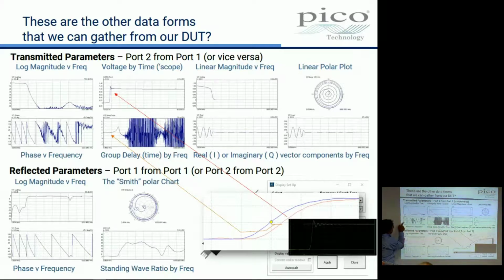Right, this is phase, and it's incrementing linearly, isn't it? And if I did what's called unwrapped phase, this is wrapping round a circle, isn't it? So this is wrapped phase. It's going round and coming round the circle. But if instead I unwrapped it and went further up in degrees, as I go around the circle, I go 360, 720, circle after circle.